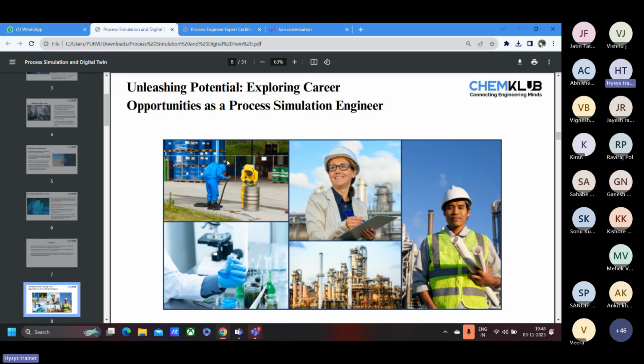So, for example, there are three screens available for the panel engineers. One screen will show this model, where they can see what kind of model is running, how it is developing the result, and what results they are getting. By understanding this kind of analysis, they say, okay, now I want to change the temperature, I think my temperature is not giving me the proper conversion. Then they will change it in the DCS system. So this is how the model works at the plant level.